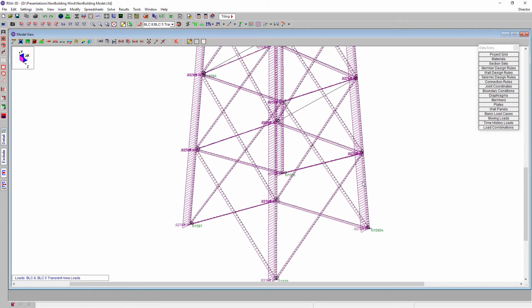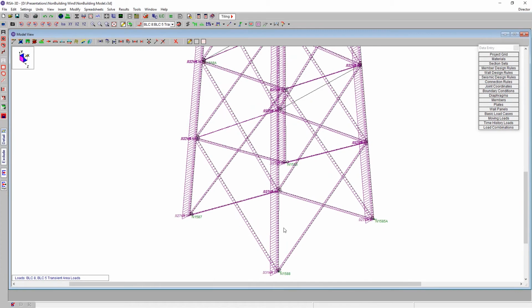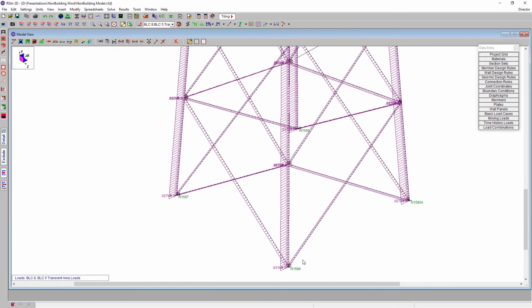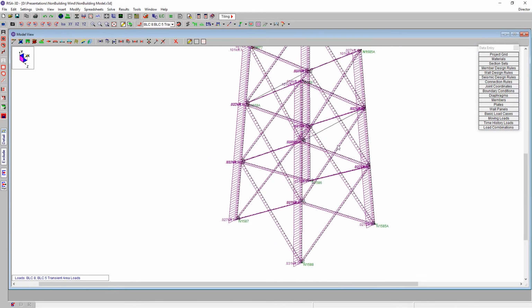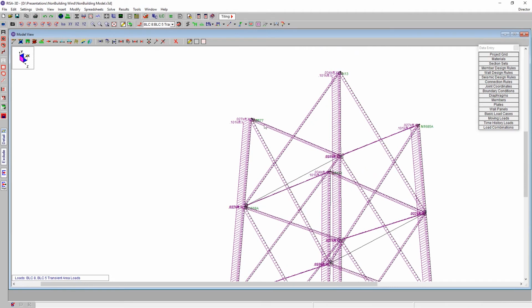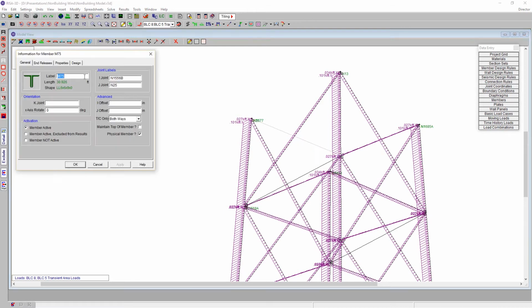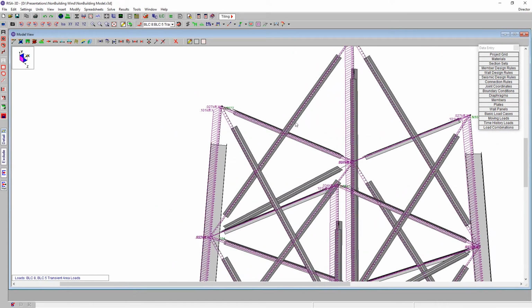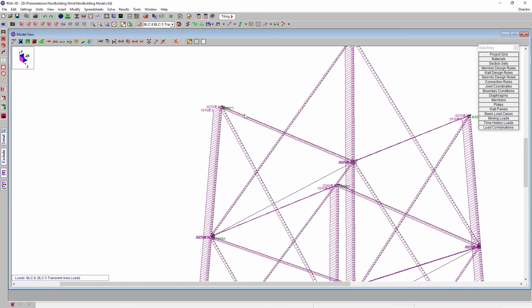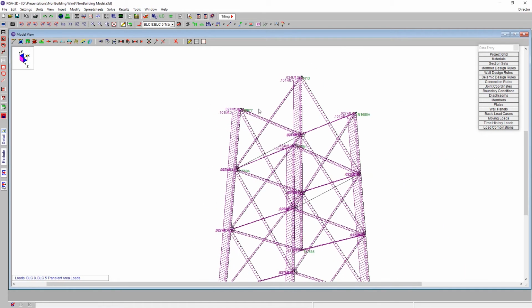And so we see here we have a line load running on all of these members, and we can see the magnitude of it. So for example, it's 0.031 down here at the base, going up to 0.027. So that's about 27 pounds per linear foot of load that's occurring right across here. And if I double click on this member, this is a 6-inch deep double angle, and let me render it so I can take a peek at it. Alright, so taking a look at that 6-inch deep double angle, if we have a load that is about 52 psf blowing on something that's about 6 inches, we're going to have something that's about 27 pounds per linear foot.